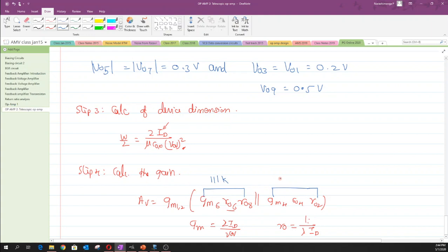Okay, so just because we have a very small impedance on one end, whereas the other one is almost 6 times higher than the impedance we got from the PMOS structure, it leads to an imbalance in the output impedance, due to which the gain ends up having a value equal to 1426 volt per volt.